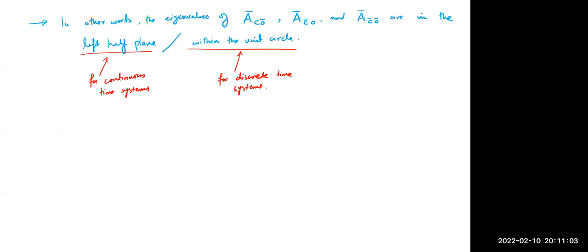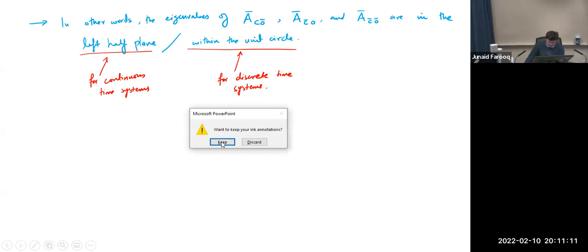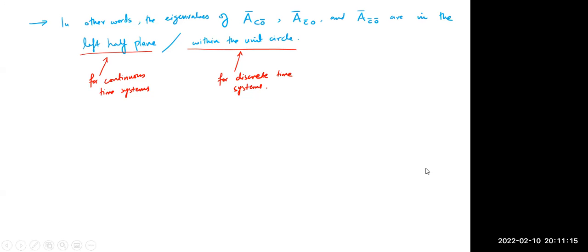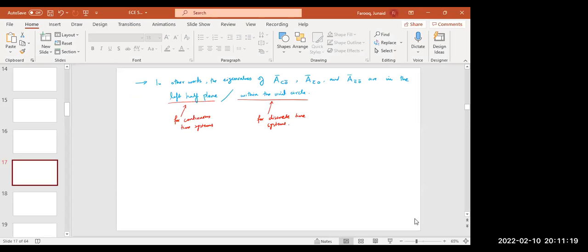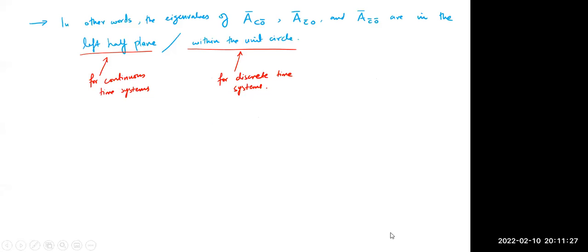I have a question. It's more general. For both controllability and observability, we use the controllability and observability matrices respectively. But for controllable decomposition and observable decomposition, we use the similarity transformation, which is extracted from those matrices.